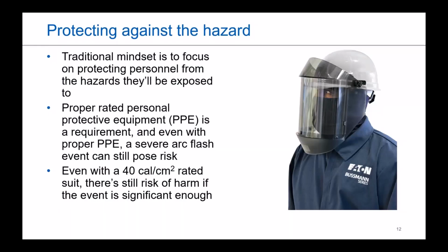And I mentioned a little bit about PPE. That's historically how folks protect themselves. It's making sure you've got the right rating on, and that when you're going out and working on equipment, the PPE you're wearing is still in good condition, because that's part of it. You need to make sure everything you're wearing is still good, that it's been evaluated and checked recently. That way, if the unfortunate event happens where you're exposed to an arc flash, you know that equipment is going to do its job.